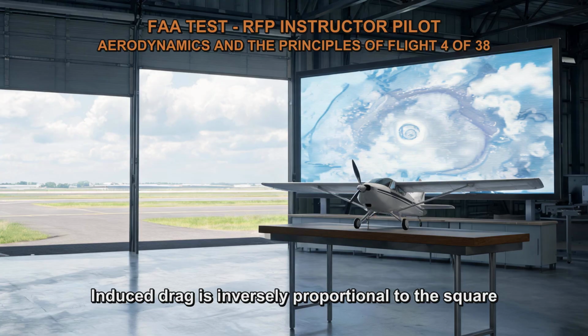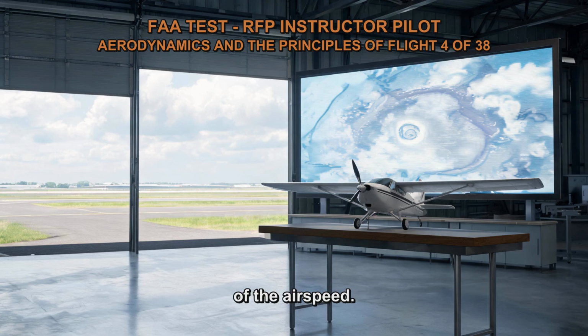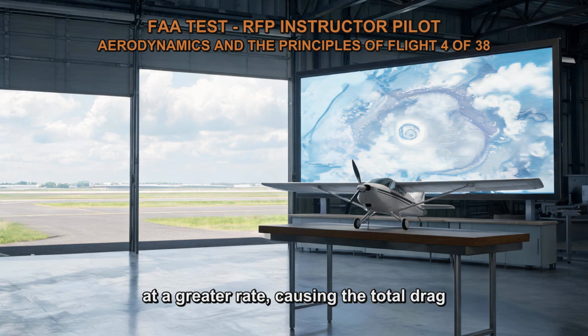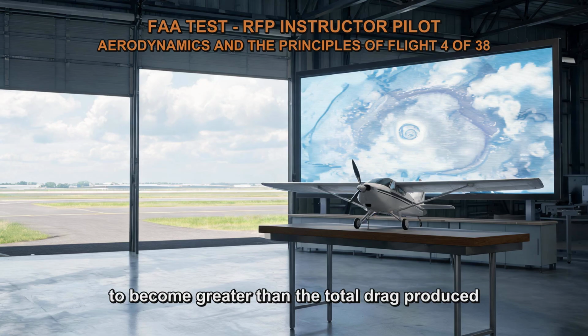Induced drag is inversely proportional to the square of the airspeed. As the airspeed decreases, the induced drag increases at a greater rate, causing the total drag to become greater than the total drag produced at the maximum lift/drag speed.